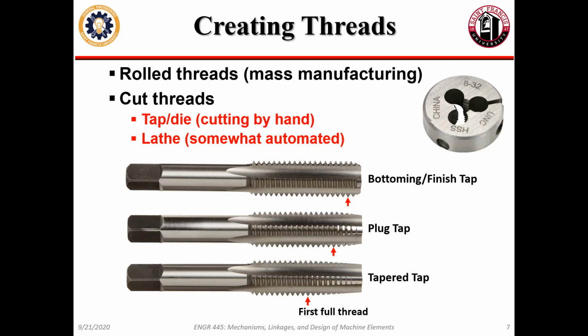So the fact that you don't cut a full thread for that long, one, helps you align it in the hole more, and two, means you cut them a little bit slower. Like you start out cutting very shallow threads and then get thicker and thicker, which is kind of nice. It helps you not break things. This is always a good deal, especially when you're cutting 6-32s. They're supposed to be the weakest thread and diameter combination out of all the American screws.